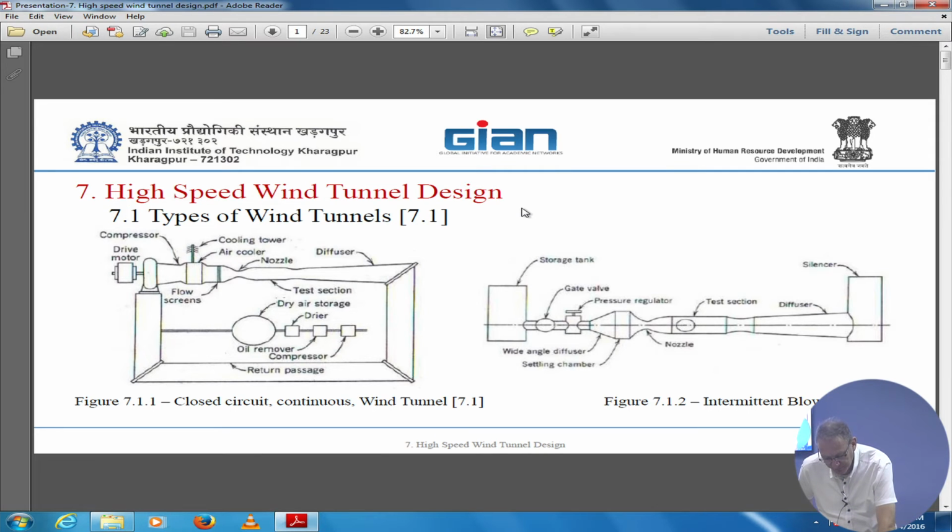Shortly, one way to decrease the pressure jump across the normal shock is to reduce back pressure to the minimum. Because if your back pressure is very low, you get a high Mach number even with low total pressure. So that's the way we do it.